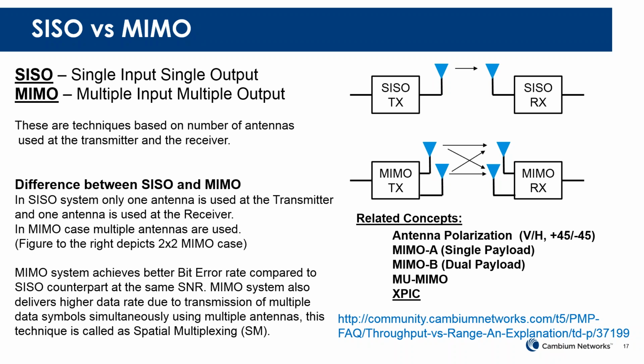So back to this MIMO A, MIMO B stuff. Depending on the environment and interference, like what Seth talked about in the prior Cambium College session, if I am able to talk with the two antennas to the other two receive antennas in a very clear path with no issues with interference, I could potentially operate in what's called MIMO B, which means I can send different information on the two transmitters, thereby doubling my capacity between those two radios that you see, the transmitter and the receiver.